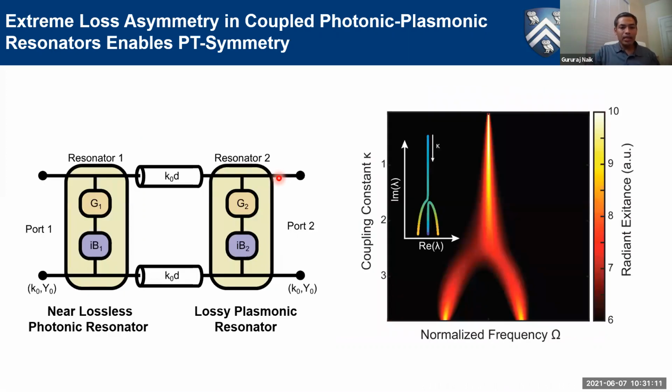And we even built a simple transmission line model, and S matrix analysis showed us that the thermal emission in fact shows exactly that PT symmetric behavior. When we have strong coupling, there are two eigenmodes. And when we go to weak coupling, we have just a single mode, but whose emissivity is nearly unity. Look at this, the peak of this emissivity is nearly 1, while the Q factor continuously increases, or the bandwidth of emission continuously narrows, as we reduce the coupling between them. So we break the trade-off between peak emissivity and spectral selectivity.